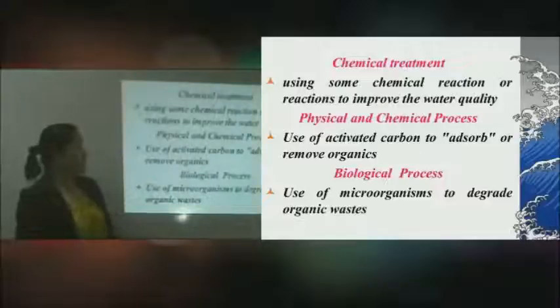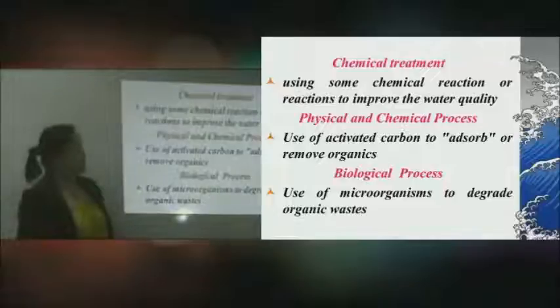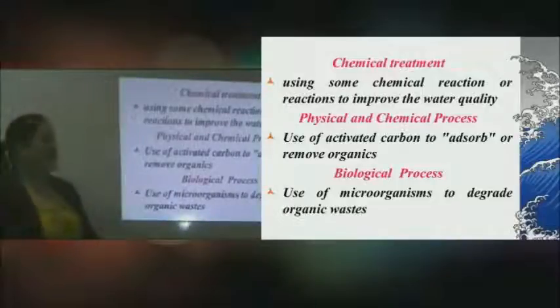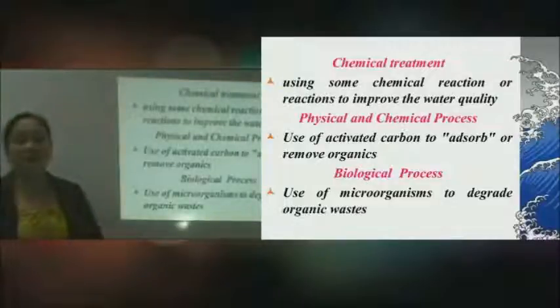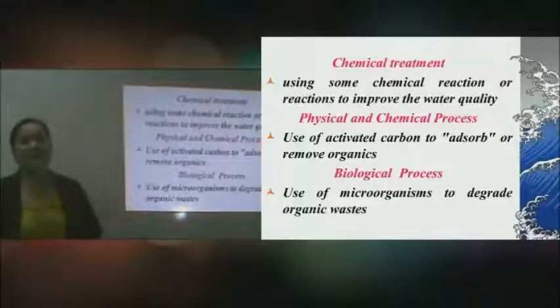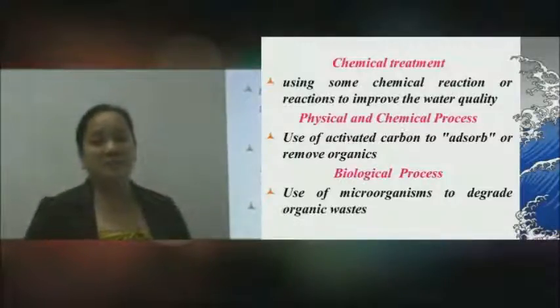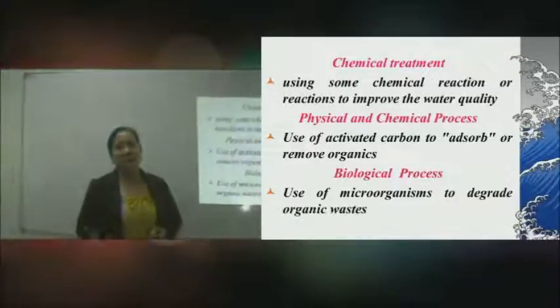Now, for the biological processes, this time, instead of using chemicals as a way to improve the water quality, you use microorganisms to degrade organic waste. It depends on what type of biological process you would like to do, and that will be dependent on the type of microorganism you utilize. You can utilize an aerobic biological process, that means involving bacteria with the involvement of oxygen. But if it's an anaerobic microorganism, that means the microorganism doesn't need oxygen to proceed.